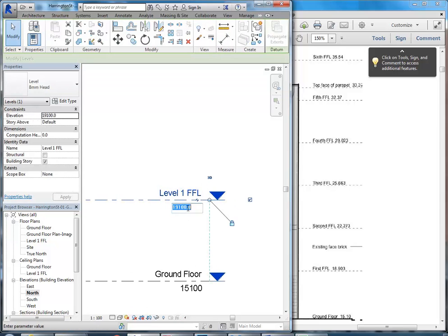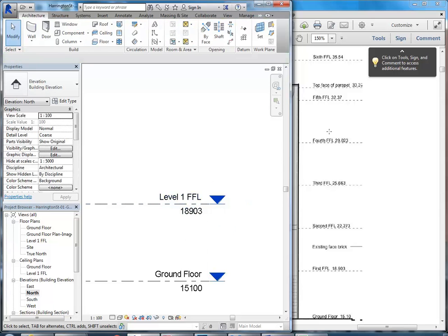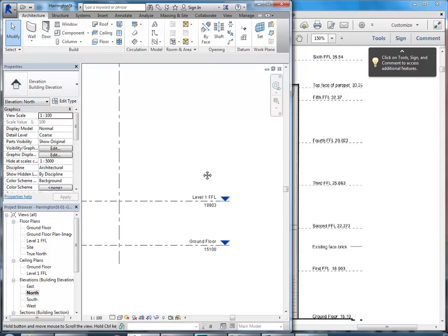And then the height. So here, oh great, okay, typical surveyors. They've done it, or planners, I don't know who's done this, but 18903, I'm sure that is the actual measurement. Normally though, you would round that off to the nearest 5 mil. Well, I'll do it like this for now, and then maybe, if you get time, or if you want to later, move all of these levels down 3 millimetres, and maybe move this one up 3 millimetres. That's a decision that you can make though. I'll do it the way it's written for now.